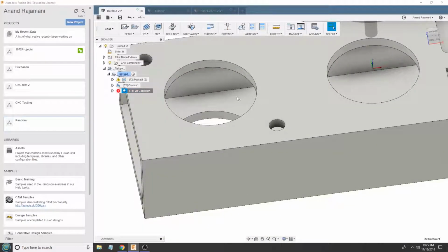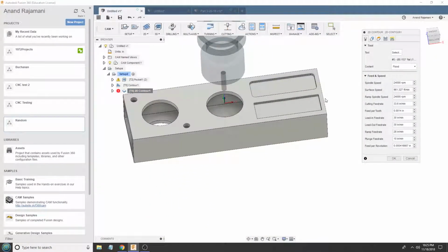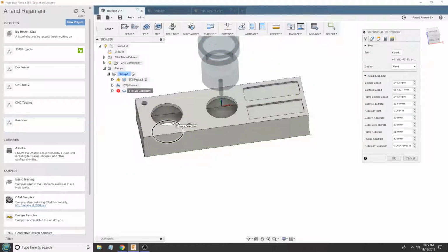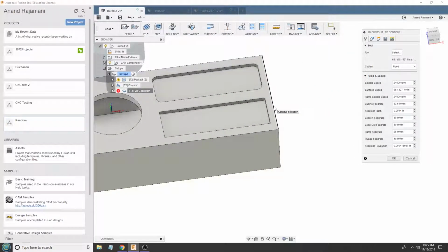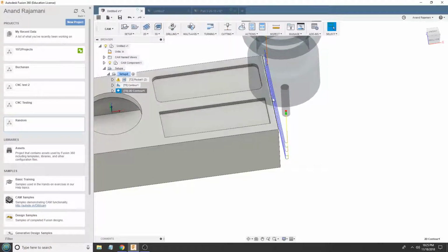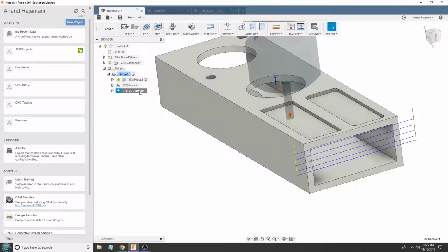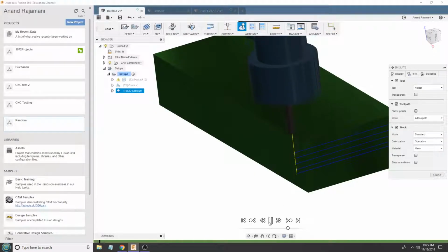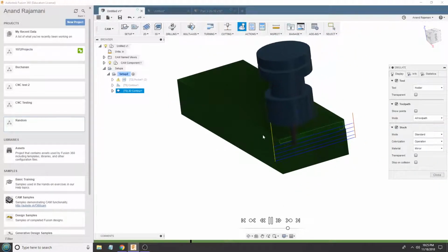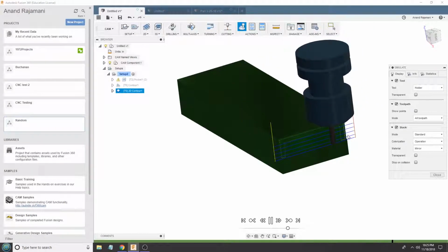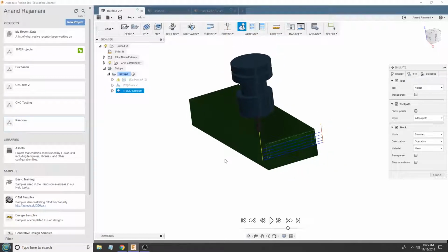It just works. This 2D contour is very straightforward. It's just where I want to cut off the tube, so if my stop is going to be on this side, I just Alt-click right here, hit OK, and this one will do my cutout operation. I've specified this to go both ways, but I've also told it to do a finishing pass. So this one will go back and forth, plunge and come back. And the final pass it does will come back right here as a finishing pass. It's a climb milling operation, so it's very good.